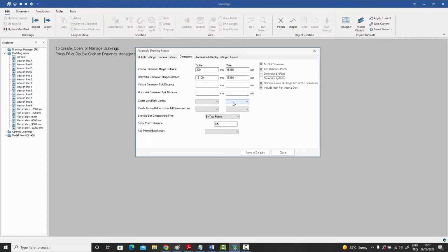The other way is, now this is obviously possible, but another way would be that if that gusset plate had any holes in it, then instead of giving the dimension of the edge of the gusset plate, it will give the dimension of the first bolt and the second bolt, let's say, of the gusset plate. Now you might think that they're basically both the same thing, but in steel detailing, parts are usually cut at a tolerance, and there can be mistakes, say about 1 millimeter or something like that.